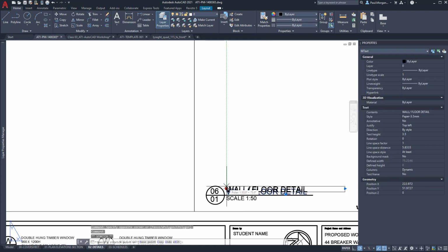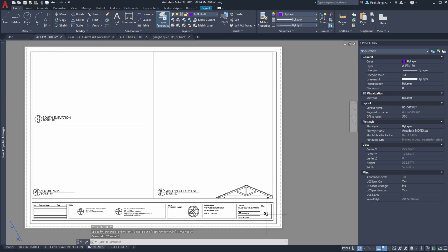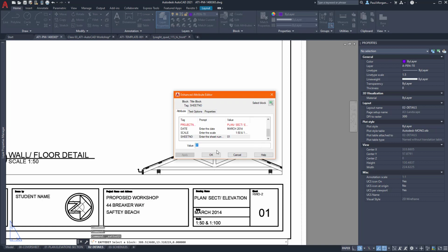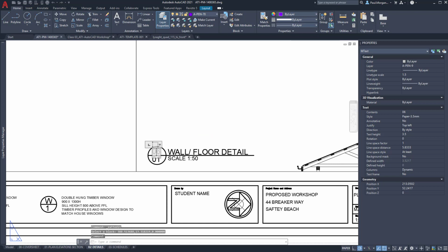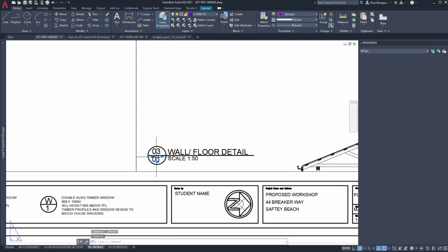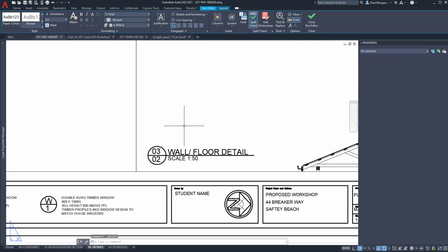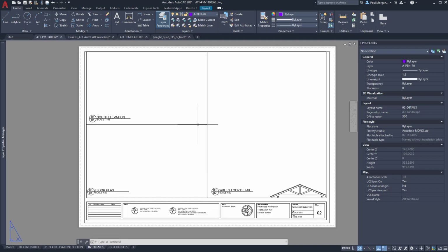Now, I don't think that's what it's called, but nonetheless, I'm just showing you how you do change that. The other thing to consider is that the drawing numbers will be different. So we're currently on drawing, this will become drawing number 2. So we need to change the sheet name, which again, you can do in your own time. I'm just giving you an example. So sheet 2, and I'm going to change this. This will be drawing 3 on sheet 2. Like so. And that's how you edit your titles, update your title block, edit your viewports, and how you scale your drawings within the viewports.